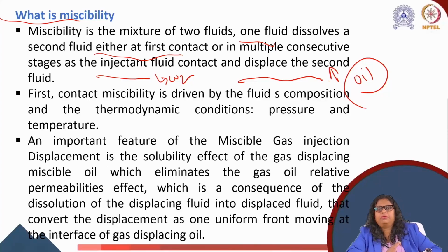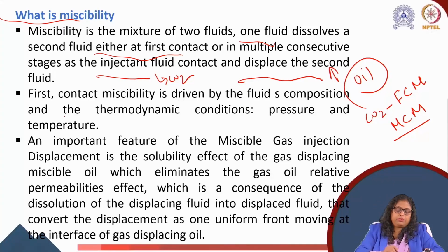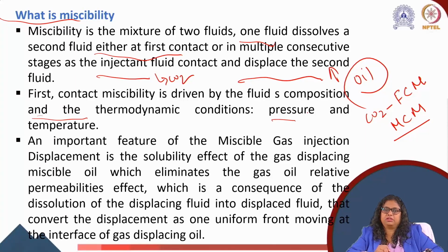There are two types of miscibility in CO2 EOR that we have seen: first contact miscibility and multiple contact miscibility. First contact miscibility is driven by fluid composition and the thermodynamic condition. For that thermodynamic condition, we have the pressure and temperature conditions.